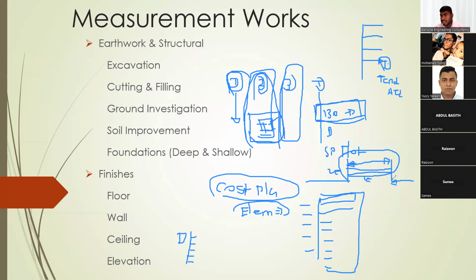Once the tender returns come to you, you make an evaluation, and you have to recommend one contractor to the client. There are two different evaluations. You have to evaluate the contractors technically, and also commercially. As a QS you don't do the technical evaluation; it will be done by a technical party. You do the commercial evaluation, then collect the technical evaluation result from the technical evaluation team, put it together, and submit the report to the client. This is also your duty as a quantity surveyor from the consultant perspective.